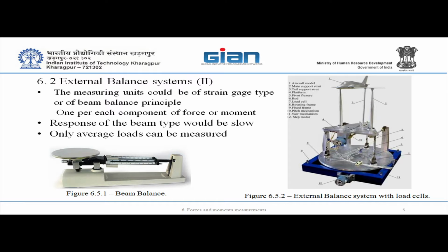What is the use of a stepper motor there, sir? In the external balance system, what is the use of a stepper motor? It's only for the movement, for the rotation and the pitching, just for 2 angles. During the test, it has nothing to do. Why not? If it's a continuous wind tunnel, you can change anything. You can change yaw angle, pitch angle. You have time, all day.